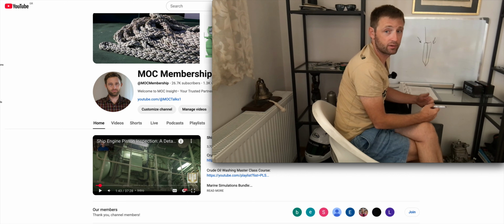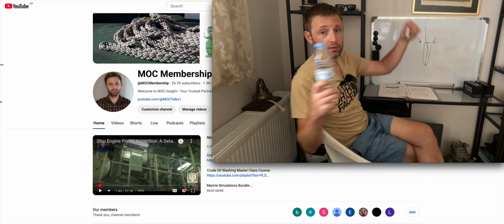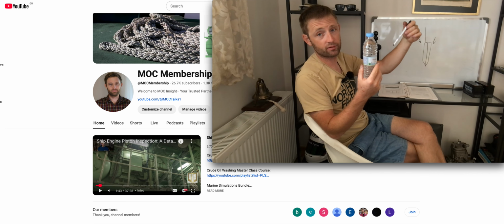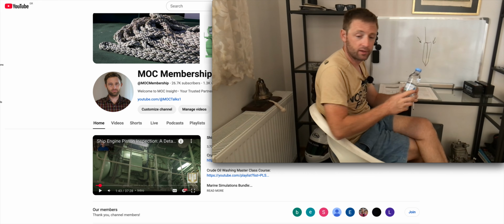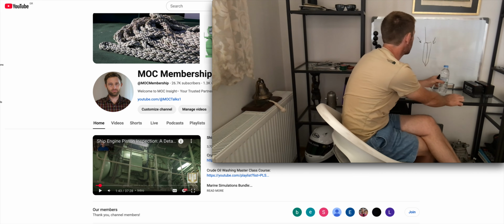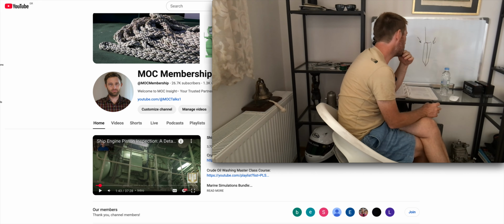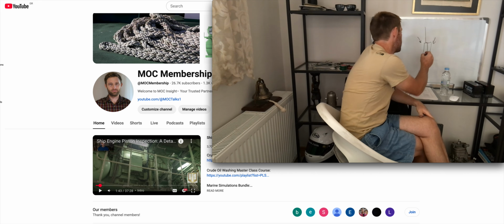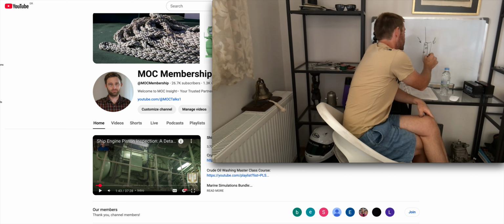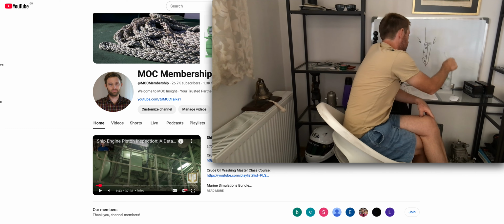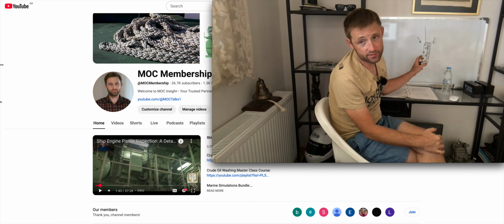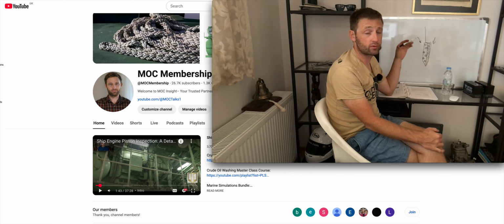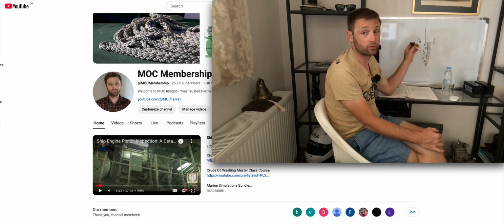Okay, I have free water, clean free water, like this one, because you are measuring with your paste, you have a reflection, or you have partial water, which is, let's say, traces. Okay, the traces will look like that, the bulb will not be filled completely here. And if you have free water, like this, it will be full coloring. Okay, different pastes react differently, so take your time to identify and verify what kind of water you have. Do you have traces or do you have water?